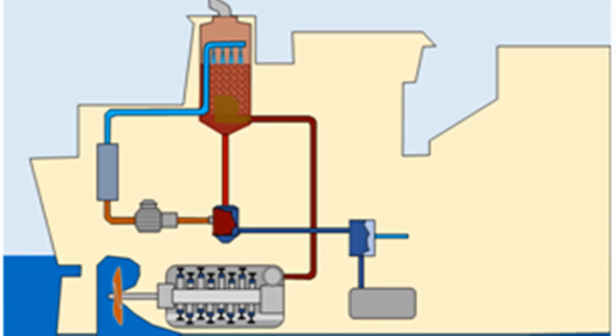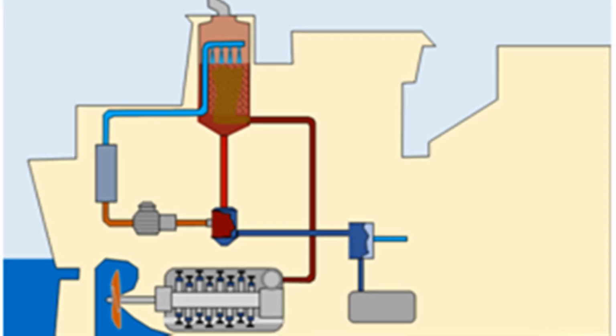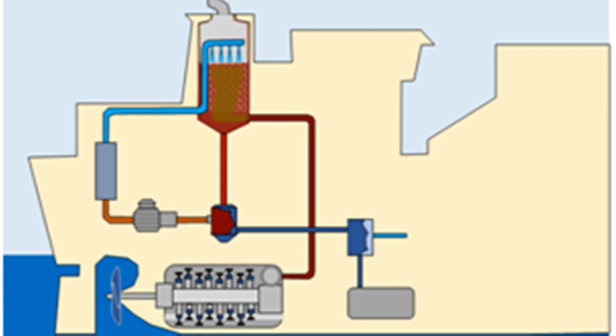So when you have a scrubber, what do you do with the SOx gases? Probably you will mix it with water or some kind of solvent, and probably the output would be contaminated water or acidic water. So are you going to pump it out? You should have two arrangements. One of the arrangements is you hand it over ashore to approved reception facilities, or you pump it out as allowed for pumping out. I mean, you are able to pump it out under the regulations of MARPOL.